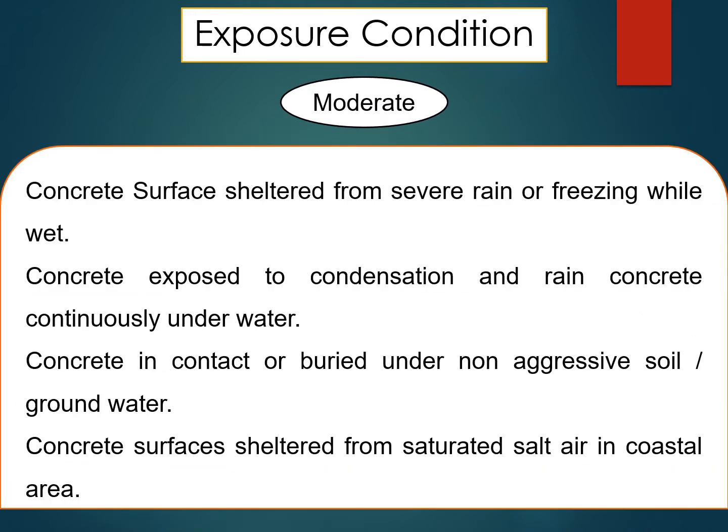Moderate exposure conditions are such concrete surfaces sheltered from severe rain or freezing while wet, concrete exposed to condensation and rain, or concrete continuously underwater, concrete in contact or buried under non-aggressive soils or groundwater, and concrete surface sheltered from saturated salt air in coastal areas will be covered under moderate exposure conditions.